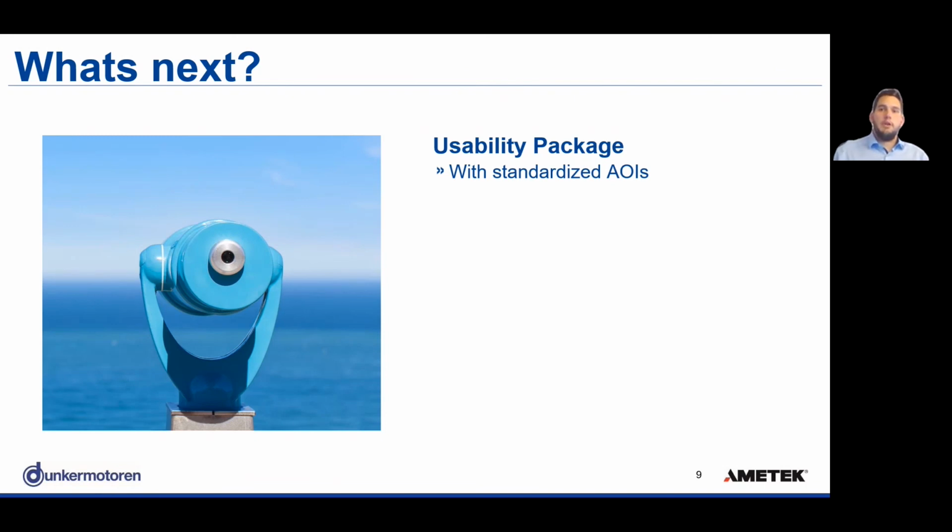Therefore, we are developing standardized AOIs, meaning add-on instructions. Those are blocks that can be directly used in the PLC code of Rockwell and define standard commands like homing or positioning of the motor or clear fault.